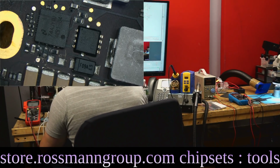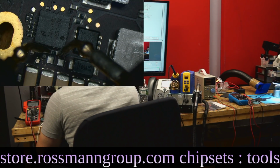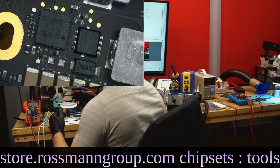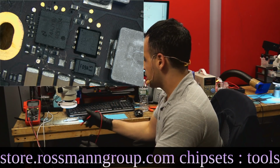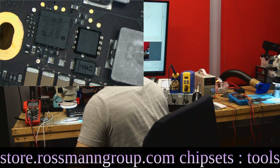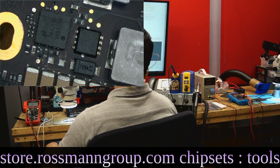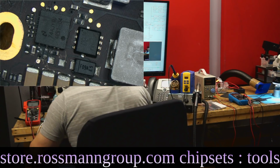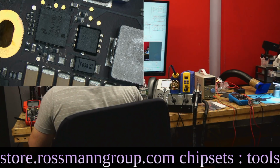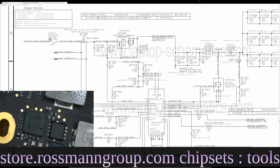So if I'm correct here, this resistor right here should measure 150 kilo ohms, and it measures 144. Of course, it's going to measure a little bit lower because we haven't taken it out of the circuit. So this most likely is a blown resistor for backlight feedback. Now, it would also lead me to question whether or not the backlight fuse is good. So I would try to see if F7700 is in this area. Let's see if F7700 is anywhere around to be found.